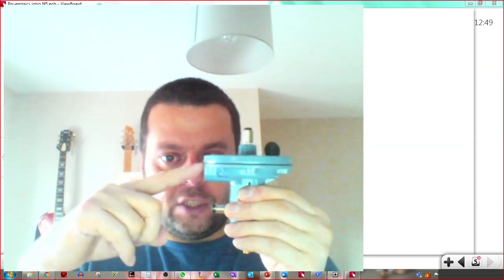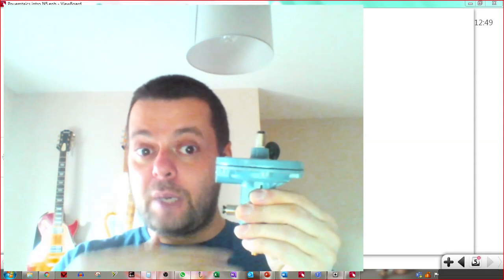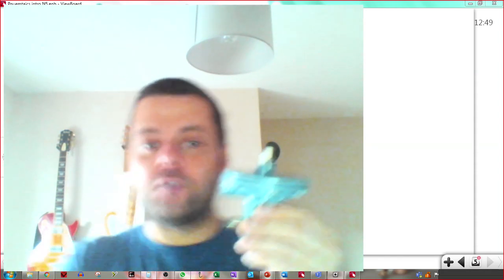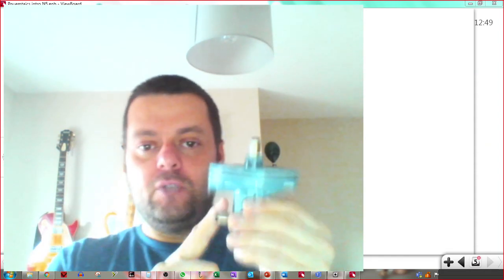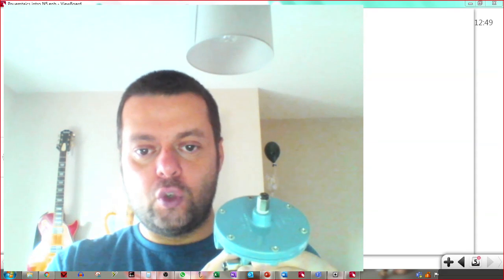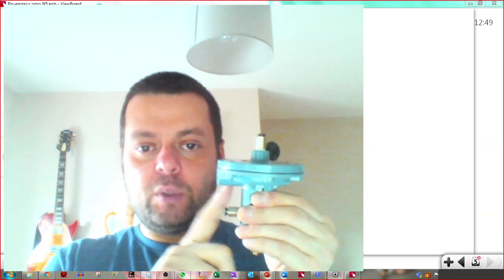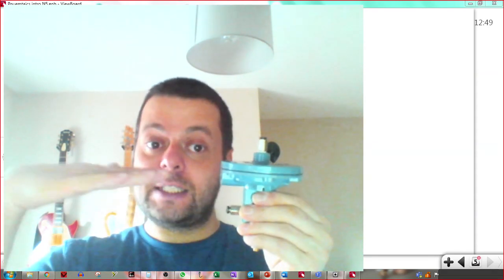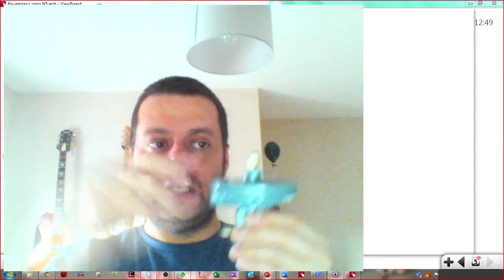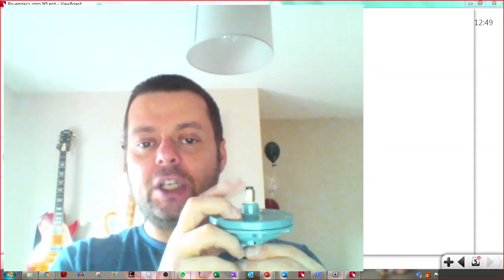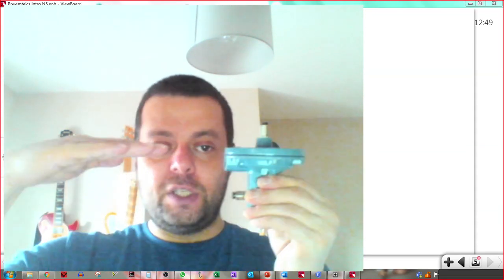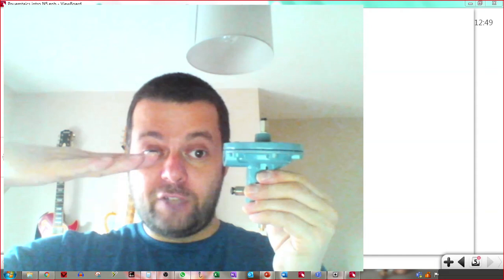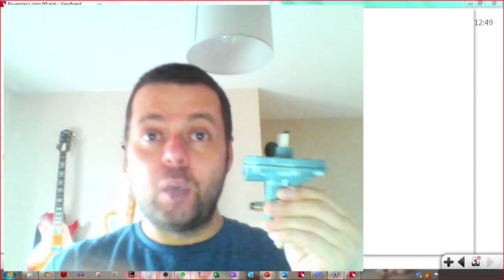That black line that runs across it is actually a circular piece of rubber that's trapped really tightly. See all the screws on there? It's trapped really tightly in between these 2 bits of metal, so it's basically a skin of tight rubber in there. And if I apply air pressure in here, that piece of rubber will start to deflect, just like blowing up a balloon.